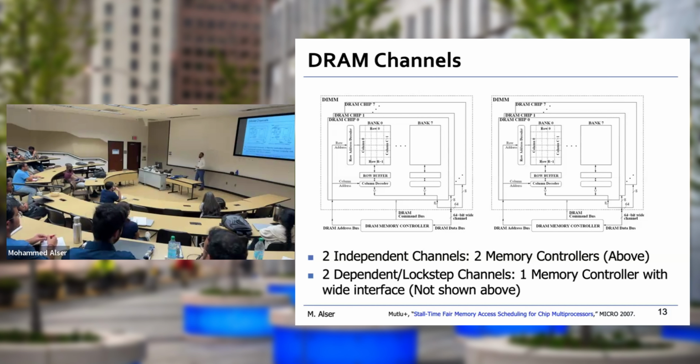Okay, excellent. All right. So to address the issue of having multiple DIMMs, we can add more memory controllers. Now we can isolate the requests into 2 DIMMs, which are really separate from each other. The first memory controller communicates with the first DIMM, and the second memory controller communicates with the second DIMM, so that we can have 2 requests in parallel, getting data at the same time from 2 DIMMs. Now we get 64 bits from here, 64 bits from there, and that is 128 bits. So this is improving the throughput, or the bandwidth, right?